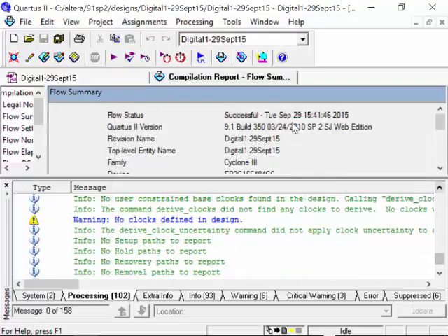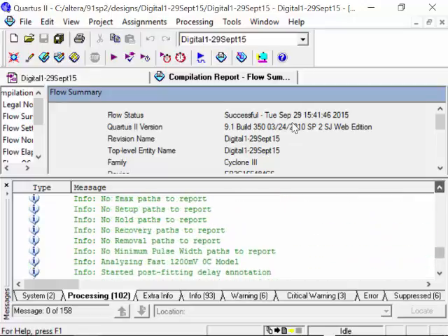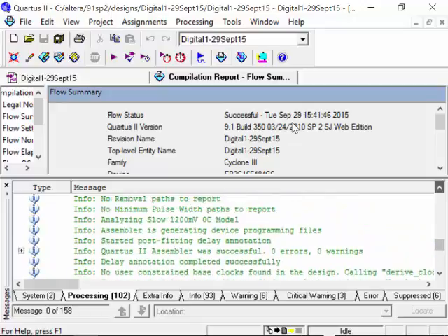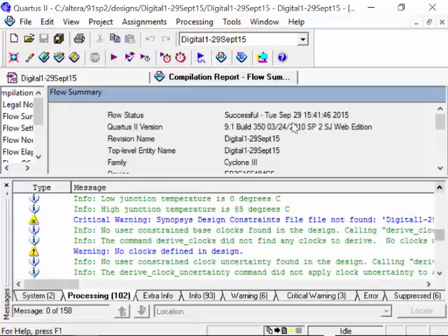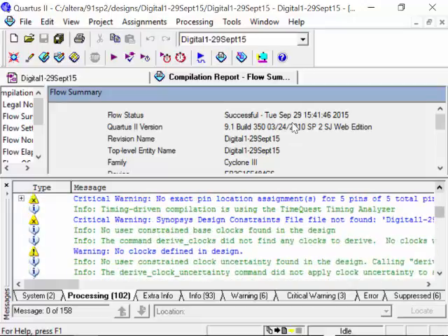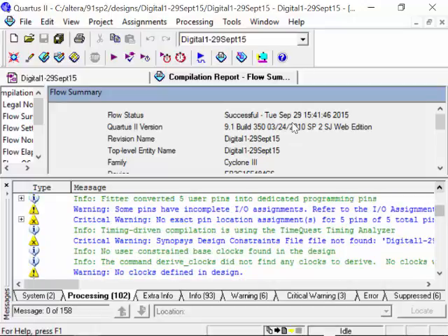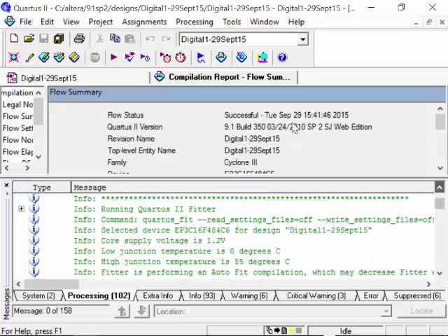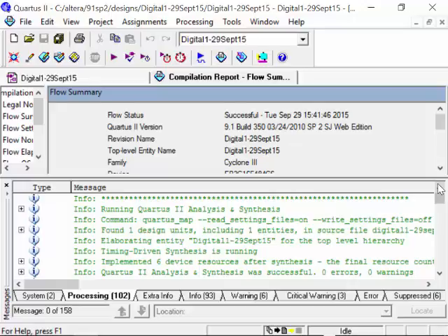No clocks defined in the design. All right, this is async. This is just a Boolean expression. There aren't any clocks, so we're not using any flip-flops here. There's no constraints file, which we don't get into here. We have not assigned our pins yet, so we will have to assign our pins. Feature lock. Okay, none of these warnings are anything we have to deal with or worry about.